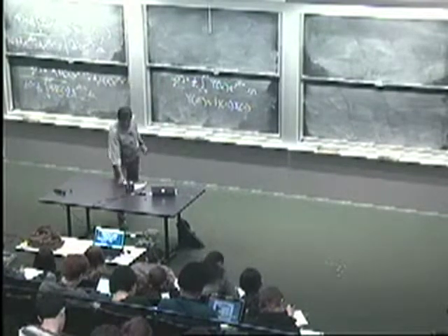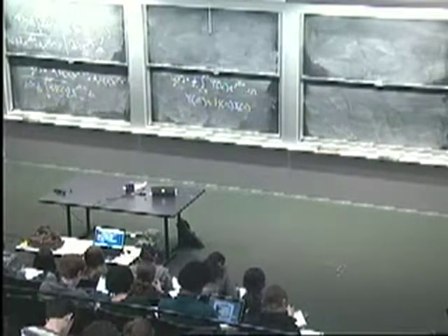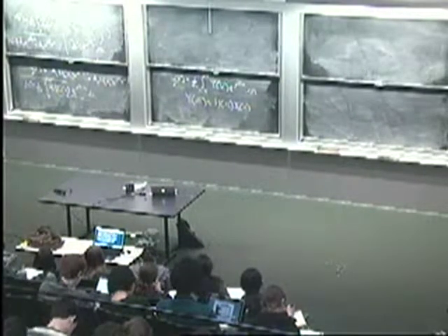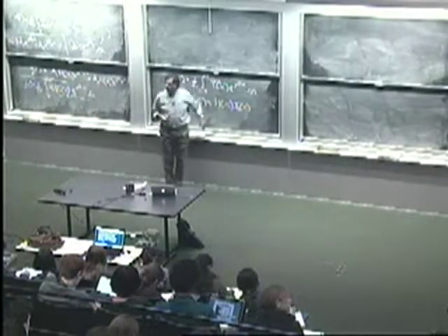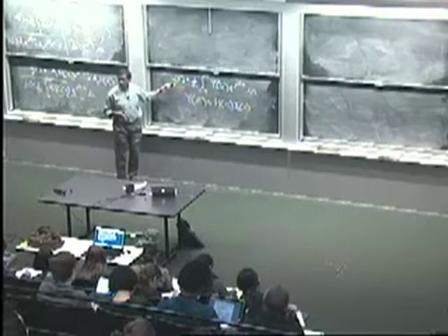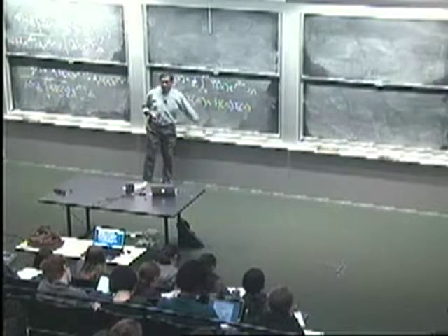Okay, so we've done a complete analysis of the input-output response of the system for essentially an arbitrary input with just a simple multiplication. So look what we've done. We've taken the input that we were given, computed the DTFT of it, which gives us the spectral content, and I'll spend some time giving you intuition for that. That's the spectral content of the input signal. What we've discovered is that the spectral content of the output is the spectral content of the input scaled by the frequency response. Okay, and once you have the spectral content of the output, you can reconstruct the time domain signal. Okay, so the big difference here is there's no convolution. You're just doing a multiplication.